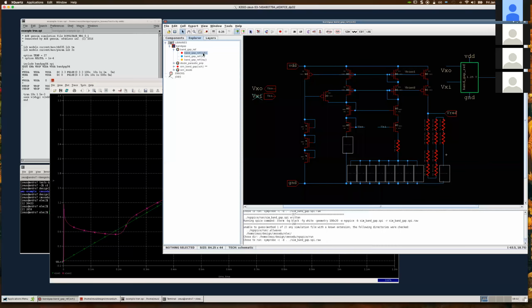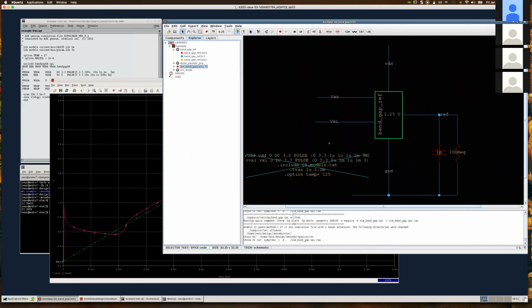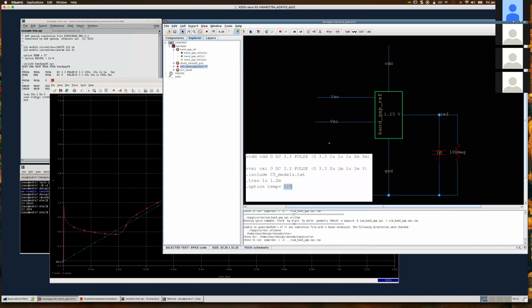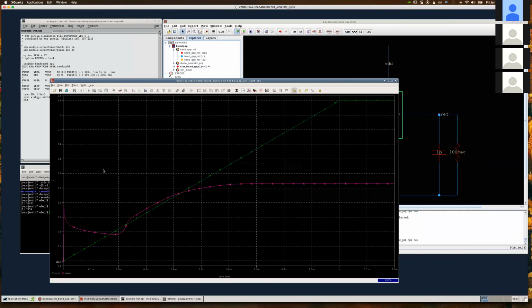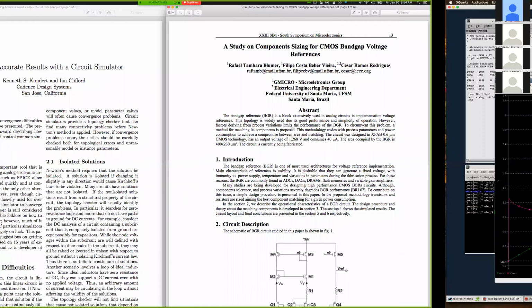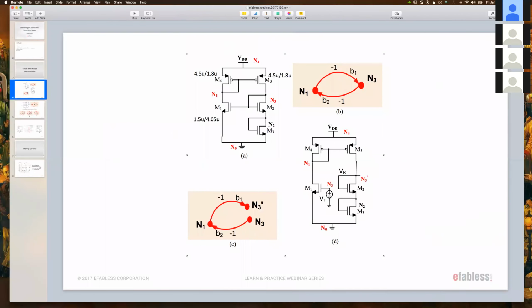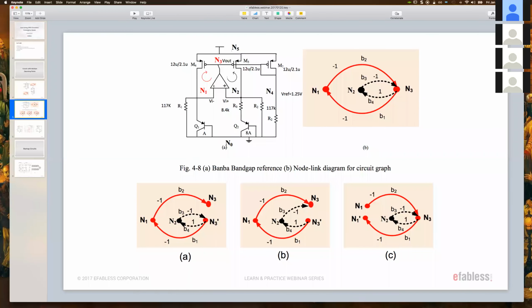So if you try such an approach and you change the temperature, it depends on the circuit, obviously, but that will change with temperature. You have to understand that if the circuit has multiple of these points, the startup circuit's job is to put it in the right point that you want. That's actually why we need a startup circuit in this case: to snap it into the points that we design for.